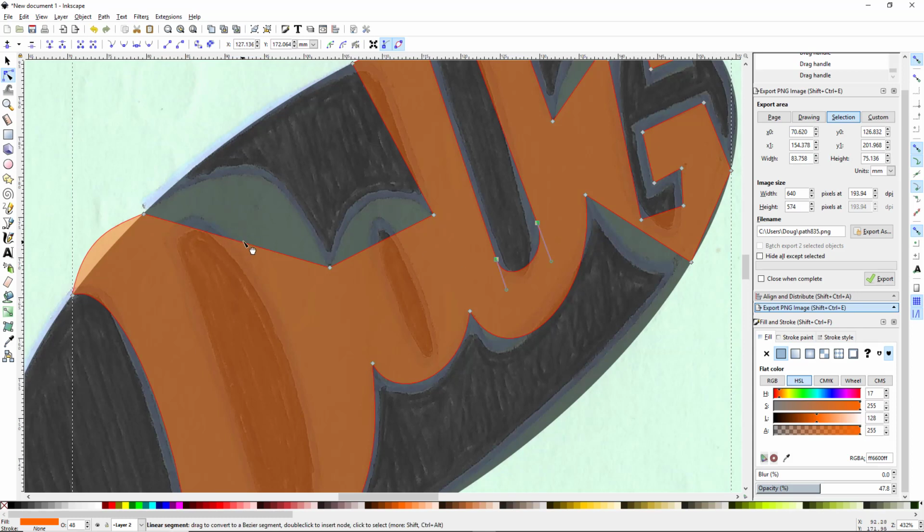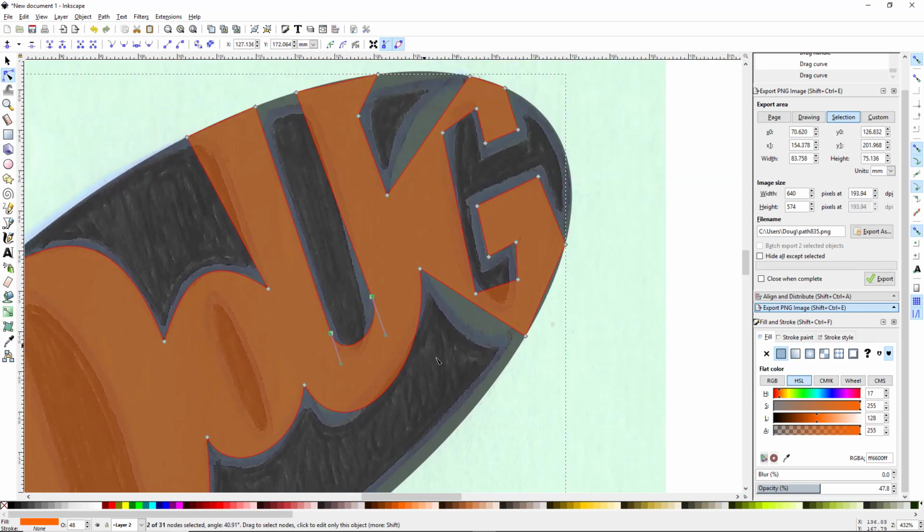We can come up here, click and drag that curve out, click and drag this one up, click in on the mouse wheel to drag this thing over, and we're just gonna finish this thing off. Here we go again. We're going to want to make both of those smooth by highlighting them and clicking on that. And if you want to move two nodes at the same time, you can, by selecting both of them. And if you move one, it will move the other as well.